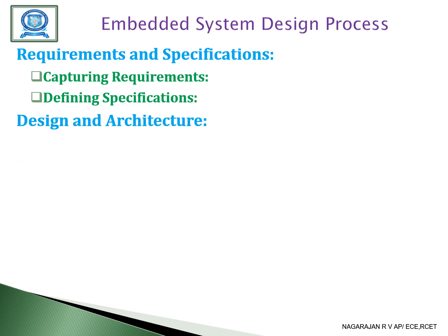And the next one is design and architecture. In design and architecture, the first one is hardware architecture. Hardware architecture involves selecting the appropriate processor, memory and peripherals to meet the system requirements. This may include a decision on the type of microcontroller, memory size, communication interfaces and power management circuits. The architecture must balance performance, cost and power consumption as required trade-offs. When designing an embedded product, an embedded engineer thinks about these constraints.